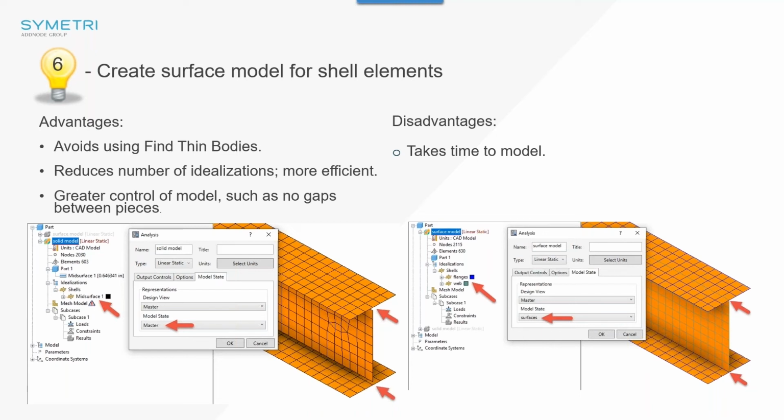Now, if you don't like that, then the only option, I'm afraid, is to create a surface model inside Inventor where you have the surfaces touching and then you have no gaps. And also the benefit of doing that method is you don't have to create contacts because you have the nodes merging and it's connected. It's a bit like having a multi-body. Whereas on the image on the left-hand side, you would have to use solver contacts with a max activation distance specified, which will cover the biggest gap.